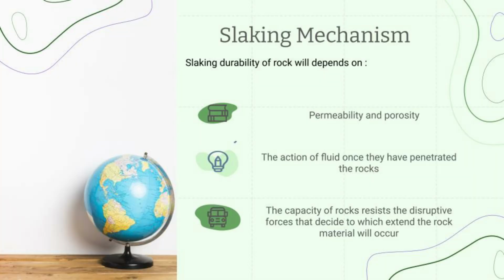Slaking durability of rock will depend on permeability and porosity, the action of fluid once they have penetrated the rocks, and the capacity of rocks to resist the destructive forces that decide to which extent the rock material will disintegrate.